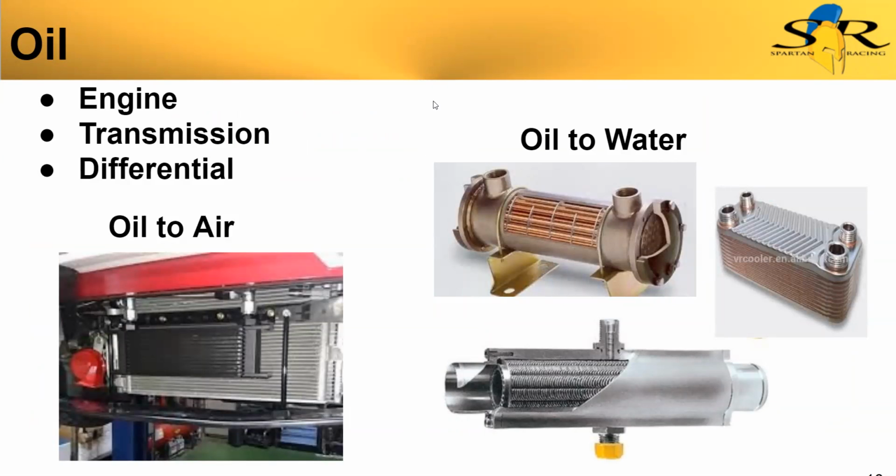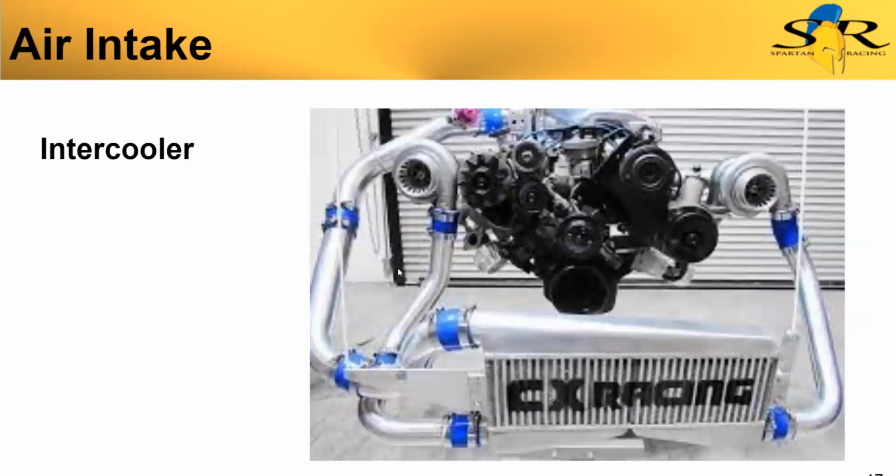And then there's oil cooling. This is still kind of part of powertrain cooling, but there's also transmission and differential coolers as well. So I'm tacking these on too, even though these aren't part of the typical main system. Some engines don't have the separate cooling systems, but the Formula car does. A lot of motorcycles will, most automatic transmissions will, and high performance differentials and transmissions will have coolers as well.